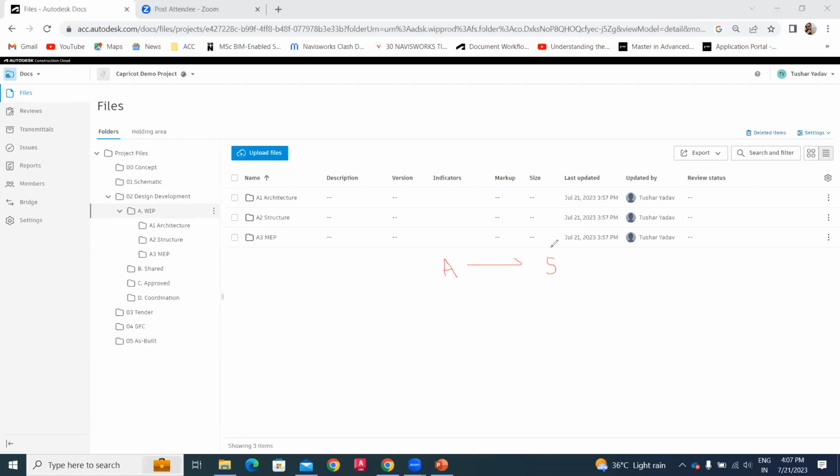What he'll do is he will delete all the structural components which the architect has placed, and he will add his own structural components like columns, beams, staircases, slabs with the right size, and he will pass on the model to the architect again. Then architect will further pass that model, which consists of the architecture and structural elements, to the MEP person or the MEP consultants.